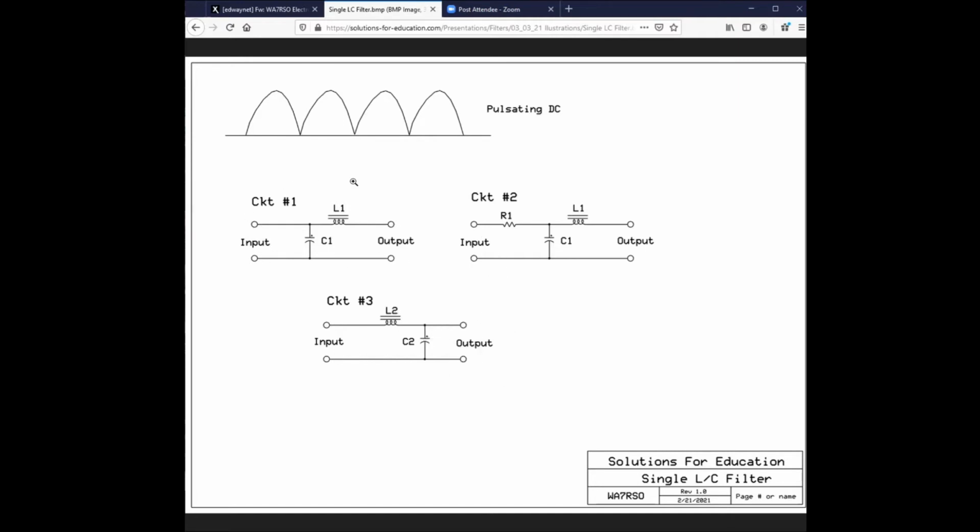All right, keywords: rate of change. You know, here's your fastest rate of change. Now, if this is only 120 hertz, what happens when you go up to higher frequencies? Let's say you go up to a kilohertz. Up to a kilohertz, you have a faster rate of change because this whole thing is happening much, much faster. Everyone with me so far?